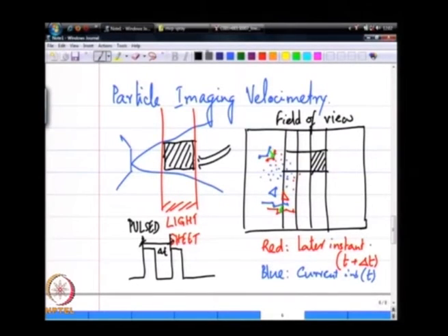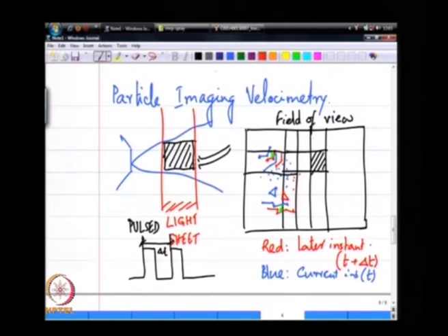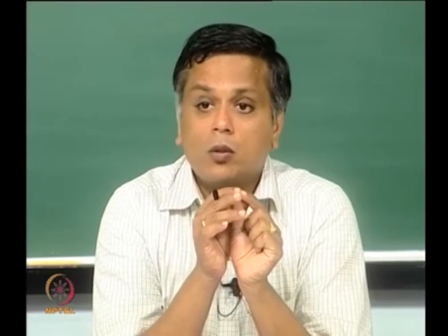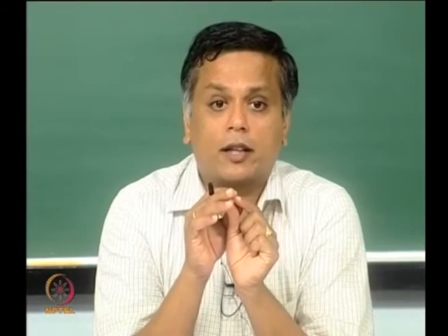So, if I took this, say for example, if those are the blue dots, these are the red dots, and if this is one of the frames, we are going to move this segment over onto itself until we get an autocorrelation peak, moving it both in the x and the y direction.